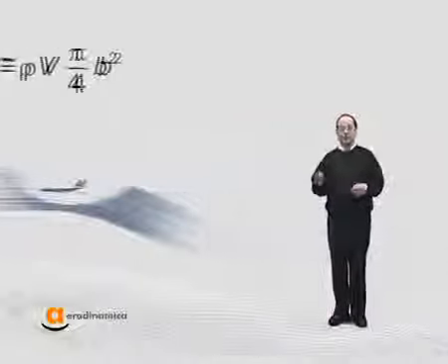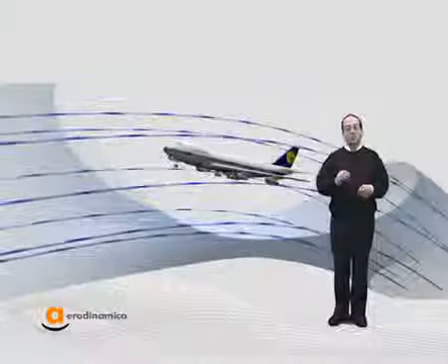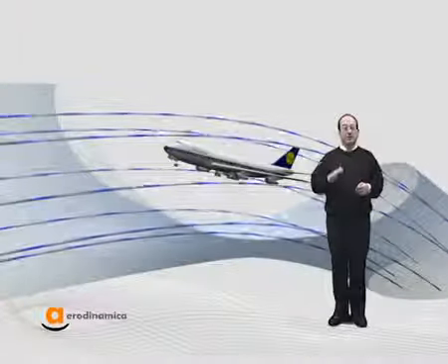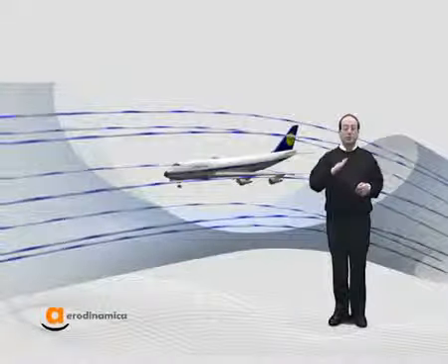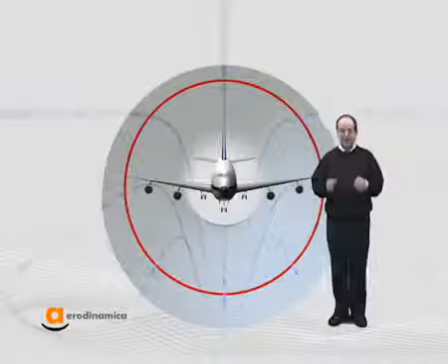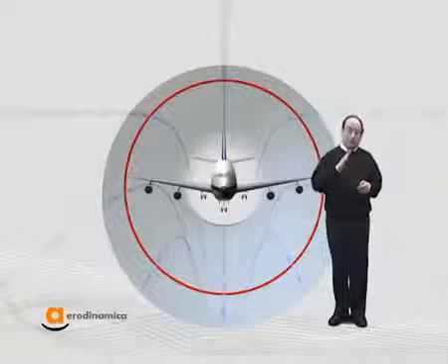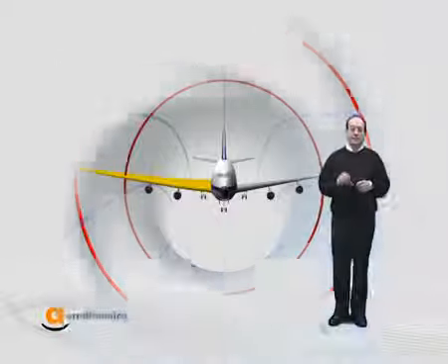and average variation of vertical speed, delta v. For example, if the speed of the airplane decreases, the vertical speed given to the air must be increased. It can be obtained by increasing the angle of attack of the wing. If we want to fly at a low speed without increasing too much the angle of attack, we have to increase the wingspan. It's now time to ask ourselves how much energy we need to have the lift.